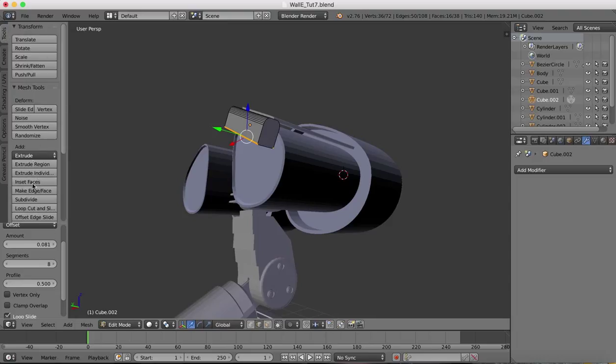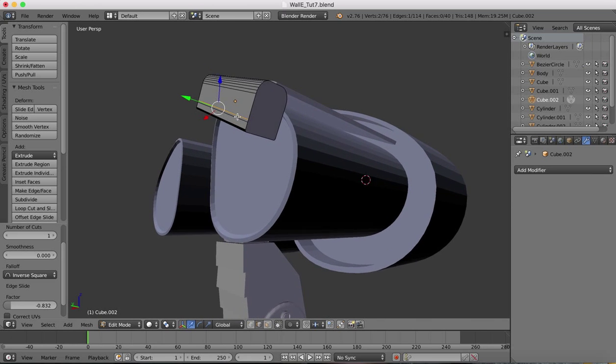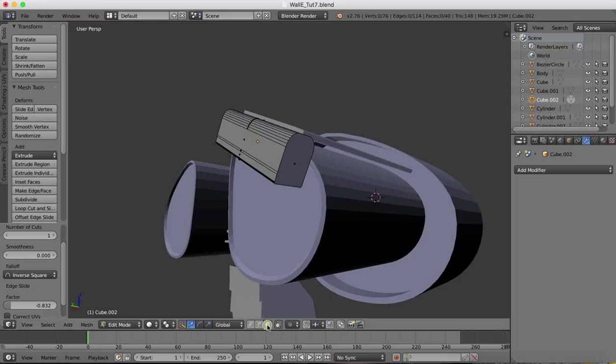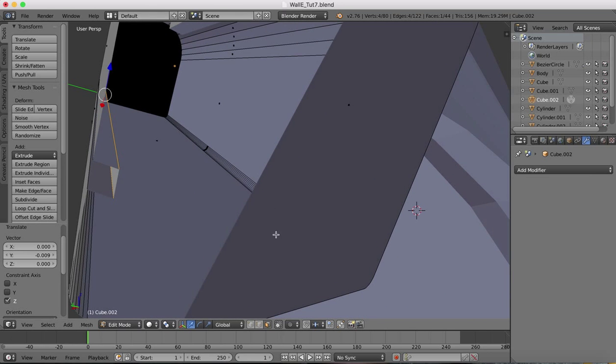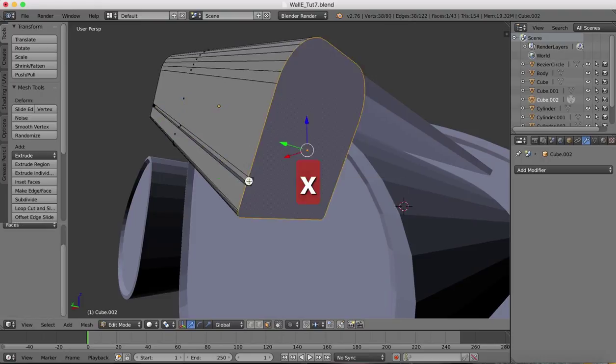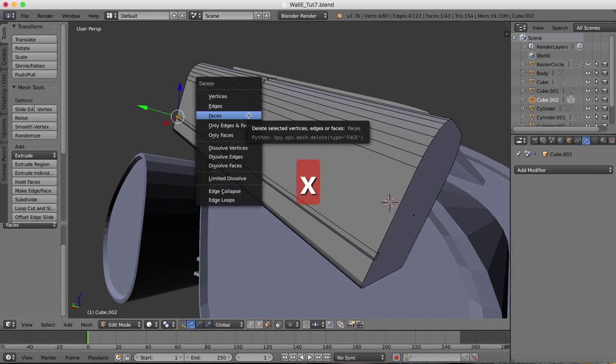Now in our tools, I'm going to get my loop cuts, and we'll place one here and another here. We'll grab that face that's been created by those loop cuts and we'll extrude it inwards a little, and then you'll see that after extruding it leaves this face here, which we can then delete. Same on the other side there.